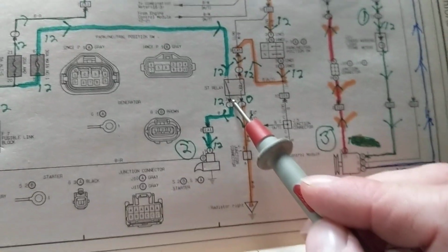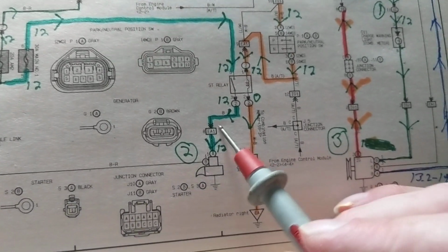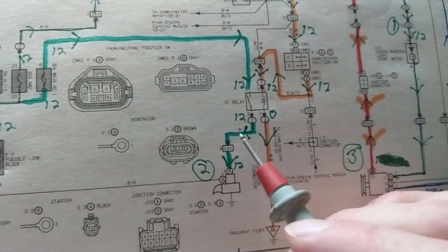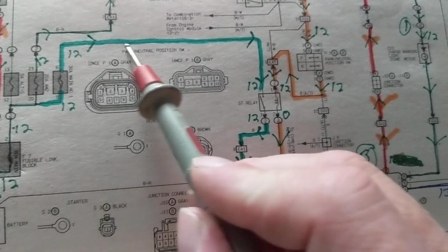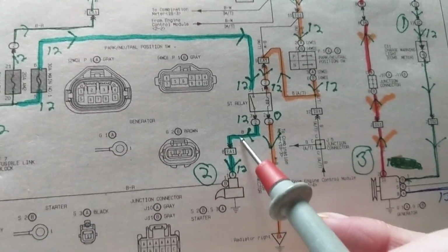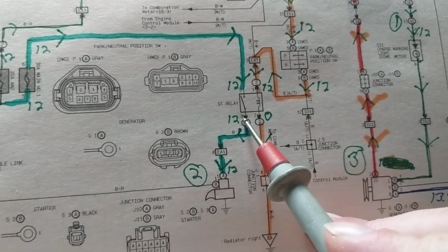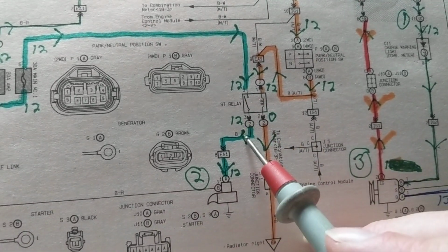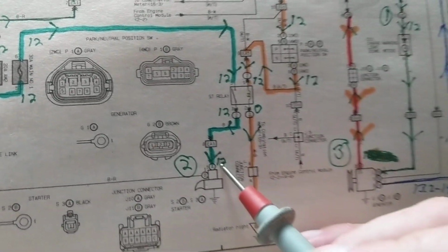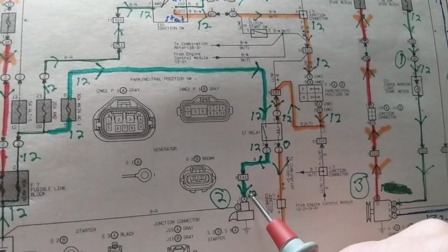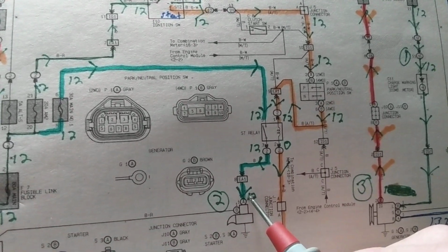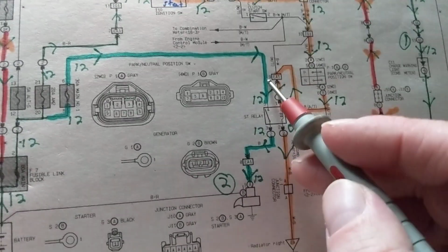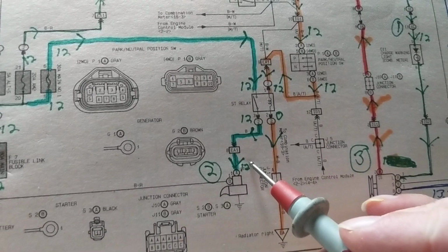We can get the load to be activated, whether it's a pump, a fuel pump, a motor, whatever it is. Current will flow now here to here. This will be closed. Starter relay. 12 volts here, 12 volts over here. How much over here? 12 volts at the solenoid. If you measure 10.5 volts, no. You have to recharge your battery. Maybe you cranked it 2 times, then it got so weak, whatever. But you first have to start with 12 volts.